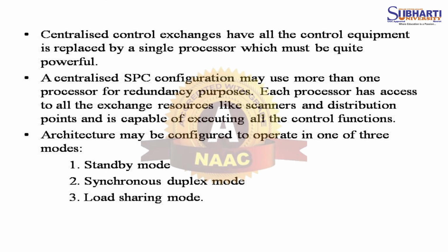In a centralized control exchange, all the control equipment is replaced by a single processor, which must be quite powerful. A centralized SPC configuration may use more than one processor for redundancy purposes. Each processor has access to all the exchange resources like scanner and distribution point and is capable of executing all the control functions. The architecture may be configured to operate in one of three modes: standby mode, synchronous duplex mode, load sharing mode.